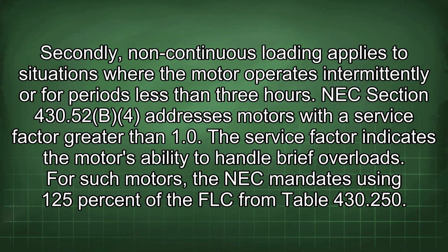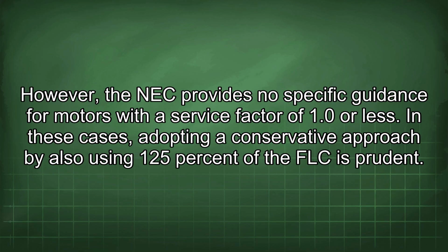Secondly, non-continuous loading applies to situations where the motor operates intermittently or for periods less than 3 hours. NEC section 430.52(b)(4) addresses motors with a service factor greater than 1.0. The service factor indicates the motor's ability to handle brief overloads. For such motors, the NEC mandates using 125% of the FLC from table 430.250. However, the NEC provides no specific guidance for motors with a service factor of 1.0 or less. In these cases, adopting a conservative approach by also using 125% of the FLC is prudent.